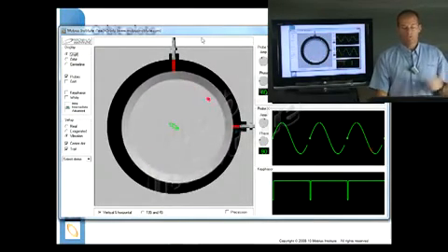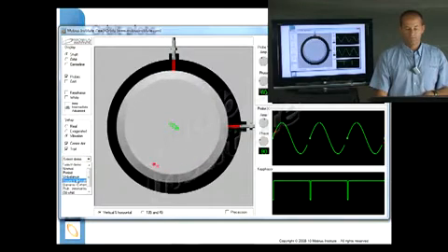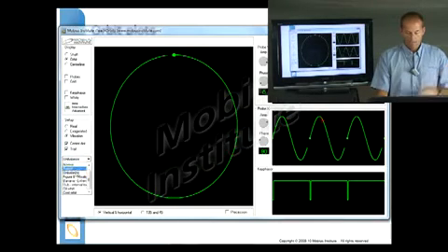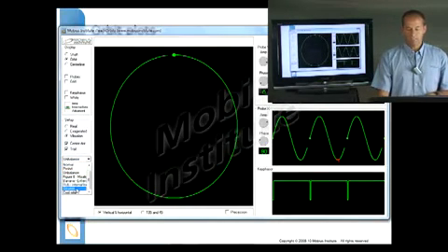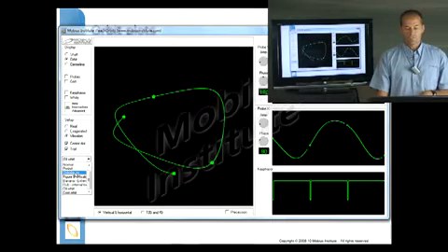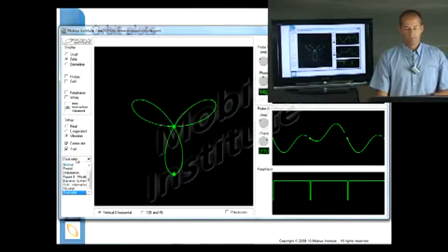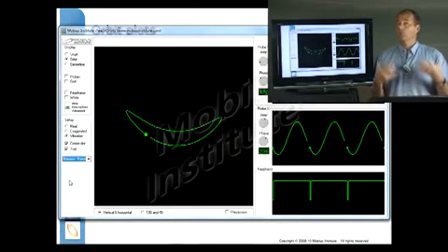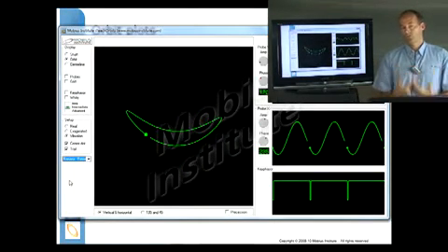And we can go through with lots of different demonstrations. If there was unbalance, there might be a lot more motion. If there were rubs or instabilities and oil whirl and all sorts of things, you get all kinds of interesting looking shapes. That's just something interesting I came up with. Just different sorts of shapes, depending on the forces on the shaft.